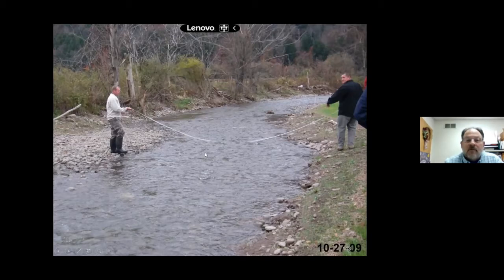It's a riffle. That's pretty important because if you get into where the pools are, the depth is going to be an issue when you're doing the survey, because you're going to find deeper areas in the pool that aren't going to be a riffle reach type cross section. They'll be different.